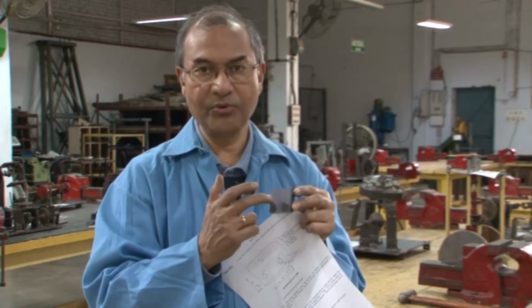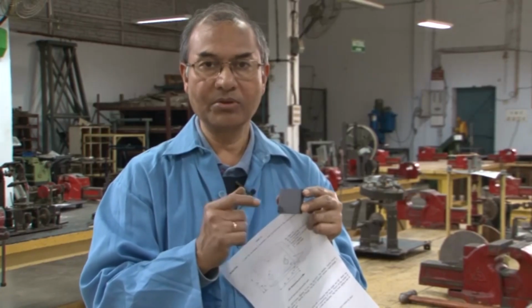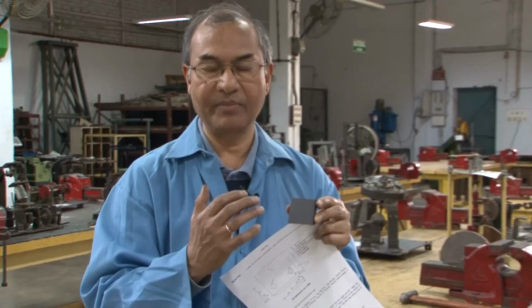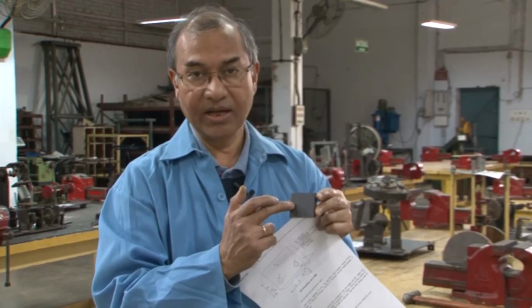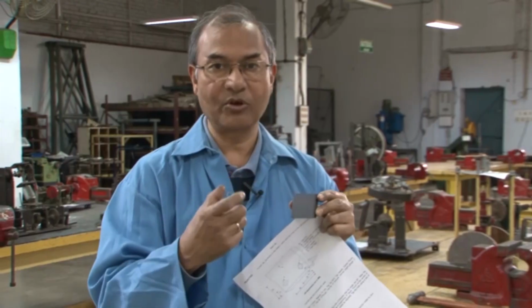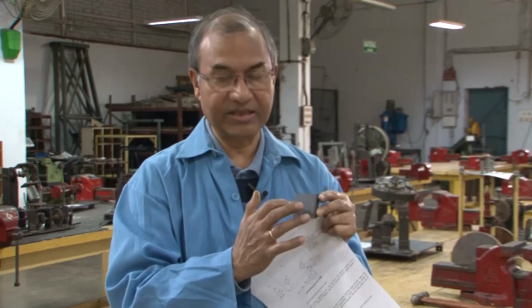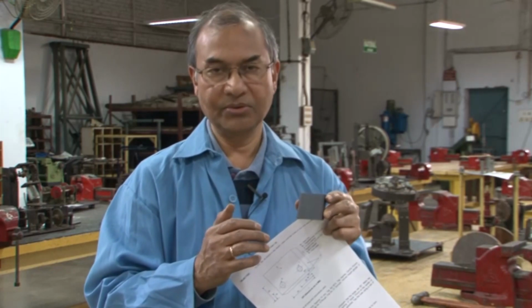So, therefore, to improve the accuracy we have to ream it first. Using the reamer we will show you how the reaming can be done. In this case we will be using the hand reamer. After hand reaming we will show you how the thread can be cut, how the internal thread can be tapped in these holes. So, there will be a tapping operation, and how this internal thread can be made. So, these are the operations that we are going to demonstrate to you right now.